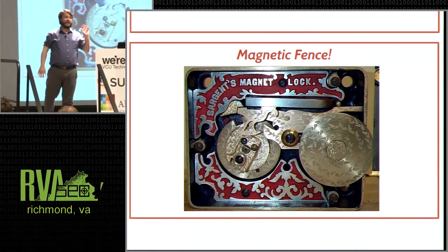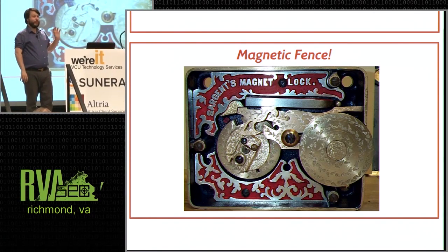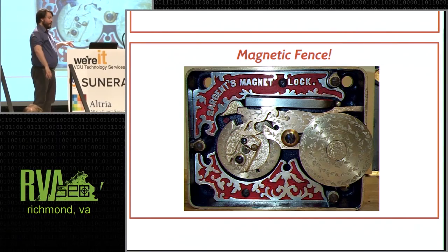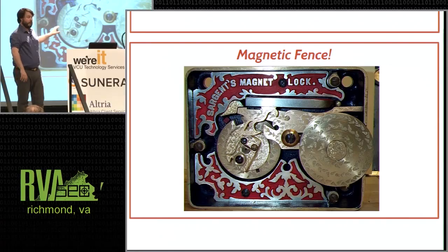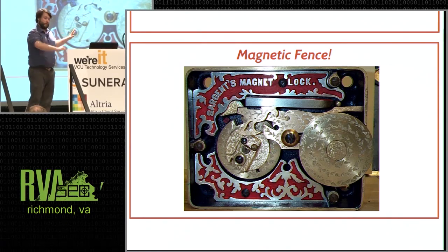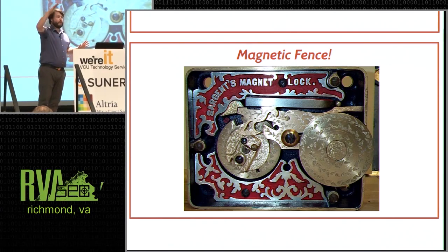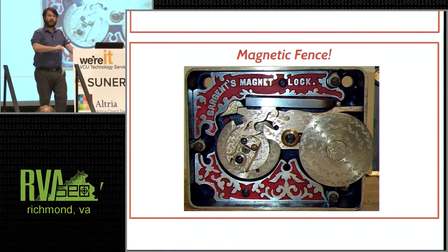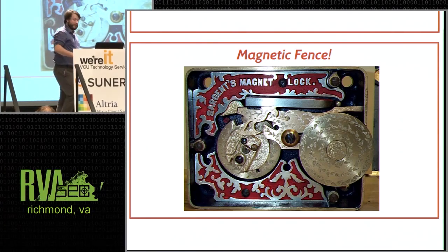And this thing is super cool. It still has a fly, but instead of relying solely on the fly riding along the cam wheel, the whole operation is actually held up by a magnet. And then once every rotation, it's separated and kicked down to attempt if the combination is there yet. So the gross majority of the time that you're rotating, the fence and the nose aren't touching anything at all. It's just every time you clear the magnet, and then the magnet picks back up again, and it becomes incredibly difficult to encode anything. At the time, at the very least, it was said to completely defeat the micrometer attack.